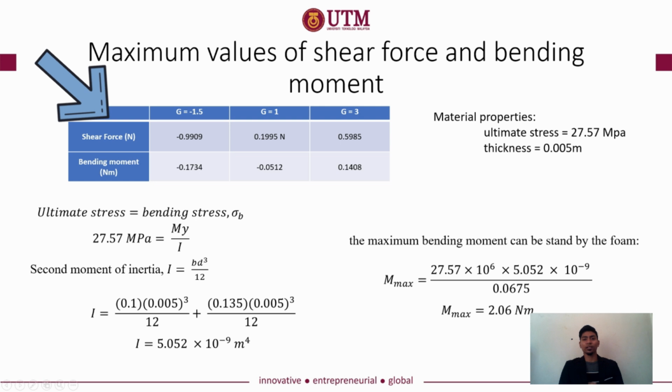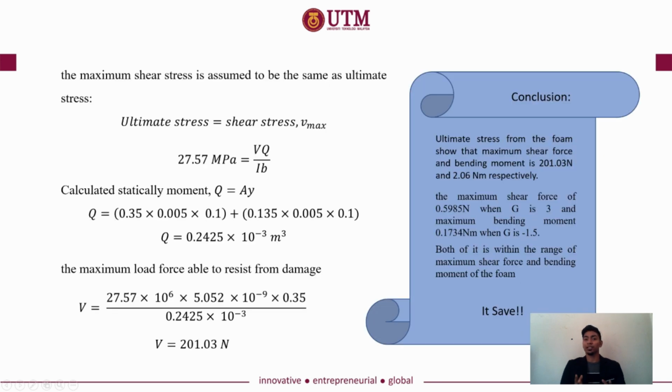As we calculate the maximum bending moment that can be withstood by this foam, we get a maximum moment of 2.06 Newton meter. By applying shear force for this condition, we get a maximum shear force of 201.03 Newton.